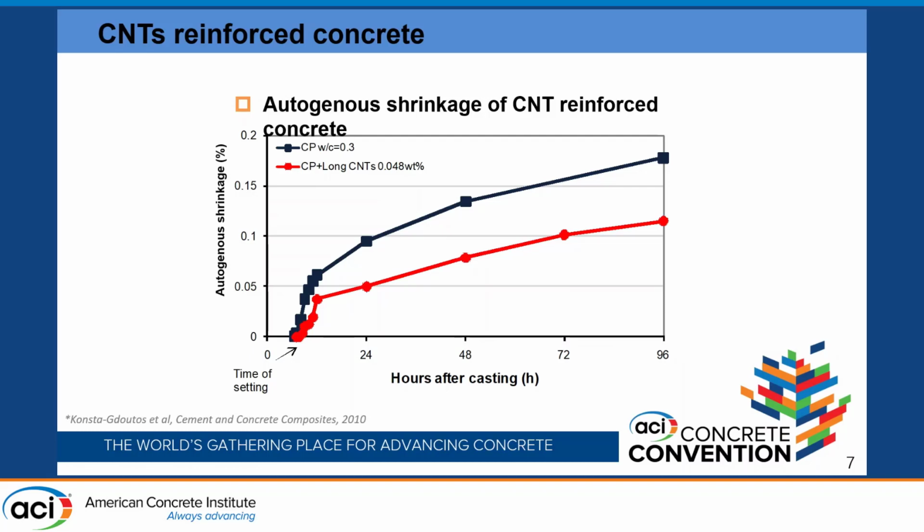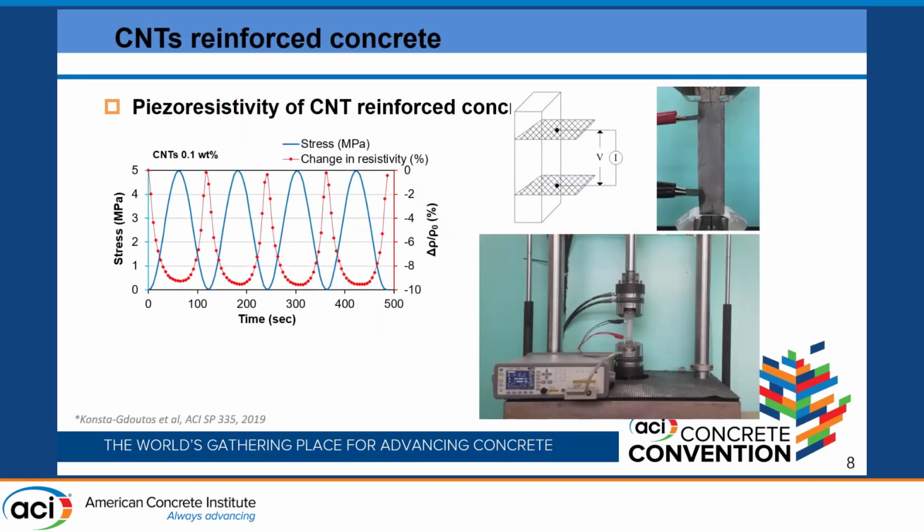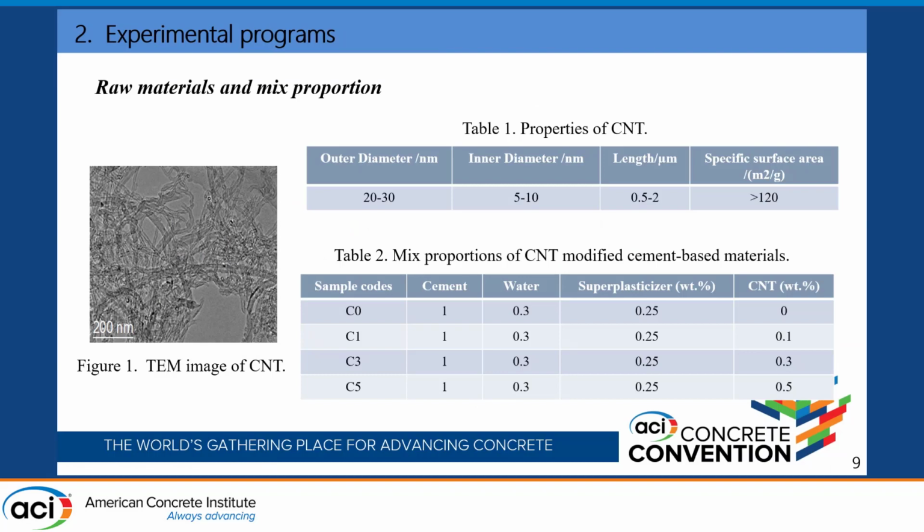For example, some work done again with Professor Consta and his group, which I had already mentioned in the previous talk, is the increase in piezoresistivity. And you can see that with addition of the CNT, we can increase the piezoresistivity as shown here.